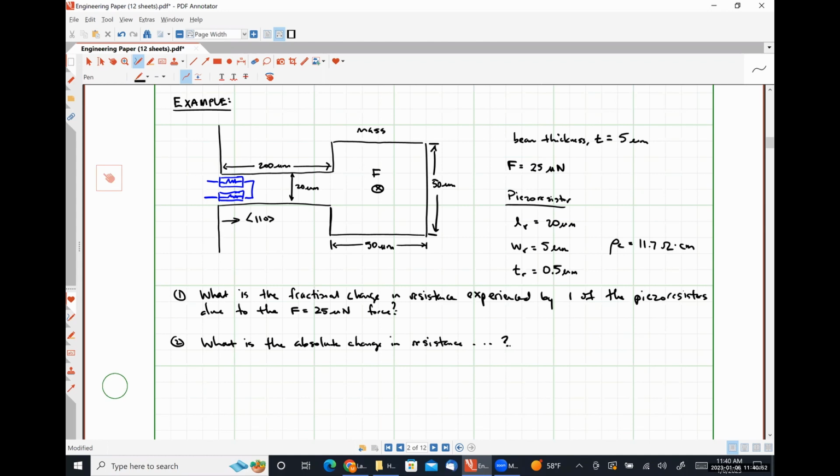So is our cantilever beam going to be experiencing longitudinal stress or transverse stress? Longitudinal, right? If there's any transverse effects, which we really shouldn't see because we're not trying to stretch the beam, they would be very small in comparison. So we're going to throw all of our transverse bits away. We shouldn't have to worry about those at all. In fact, I don't think they should exist because we're doing cantilever bending.